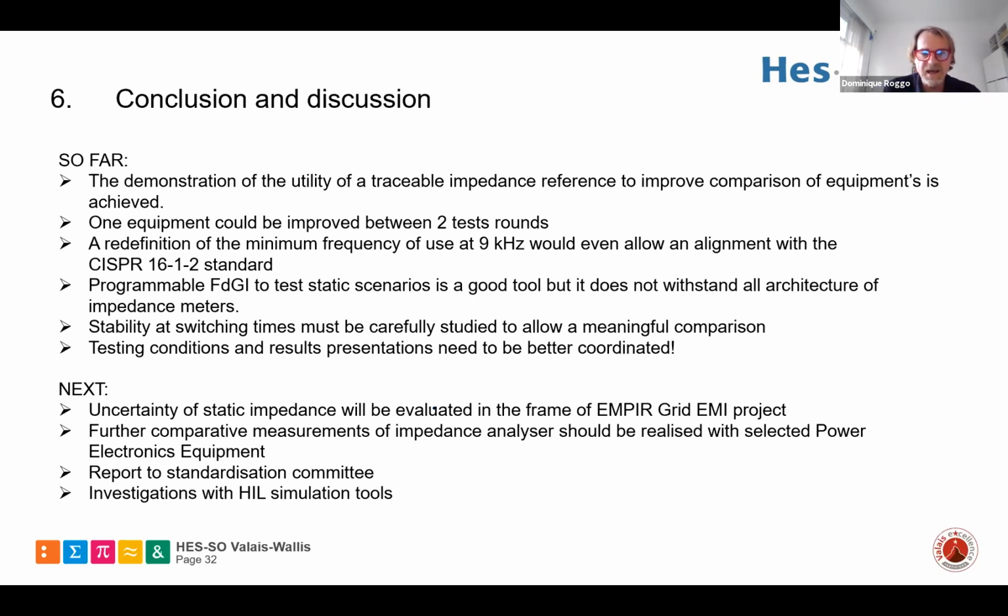Stability at switching times has really brought trouble to the tests of the programmable impedance. I think at this stage, we have a good programmable impedance, but not good enough dynamic, especially in the low frequency range. In the high frequency range, the devices and the parasitic components must also be checked.